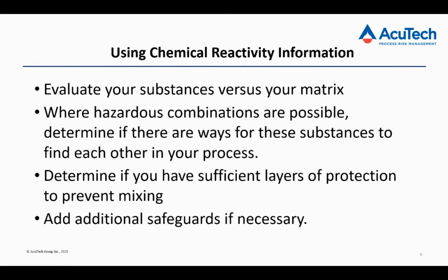So what happens after you've created a reactivity matrix? Does it just sit in a binder or a folder and get pulled out when your PSM auditor comes around every 3 years to ask about inadvertent mixing? If you haven't already done so, you really need to evaluate your processes versus that matrix. Where hazardous combinations are possible, you need to determine if there are ways that those substances can actually get together at your site. What you're really trying to do is determine if you have sufficient layers of protection to prevent that mixing.